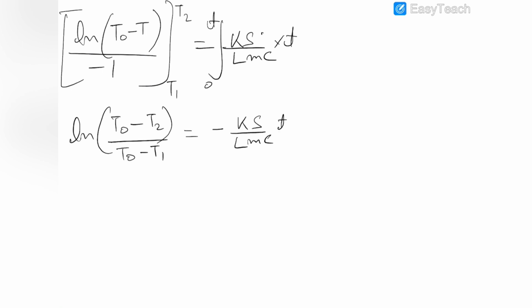So you can see that the time taken by this rod to increase the temperature of this plate from T1 to T2 will be LMC by Ks into ln (T0 minus T2) by (T0 minus T1).